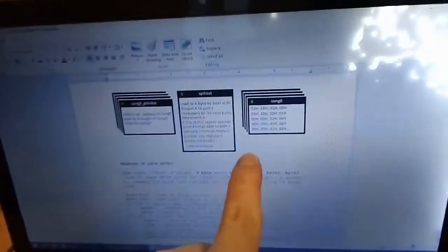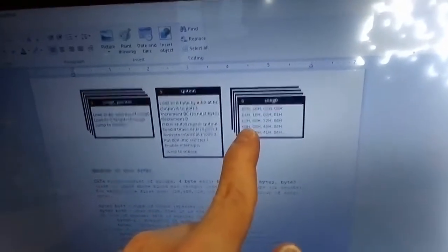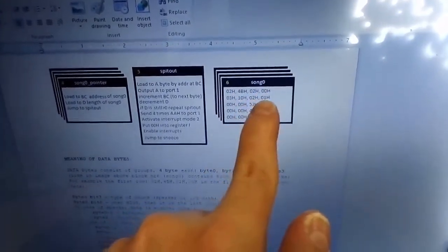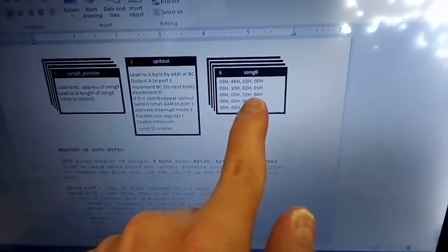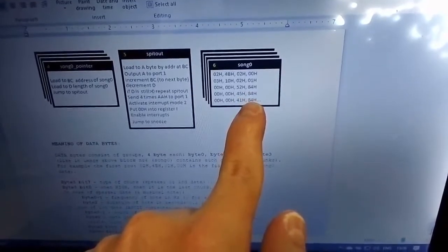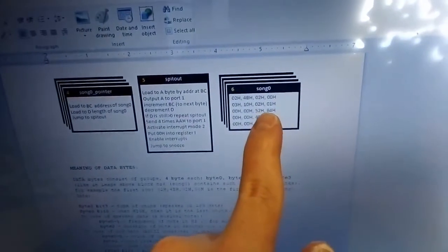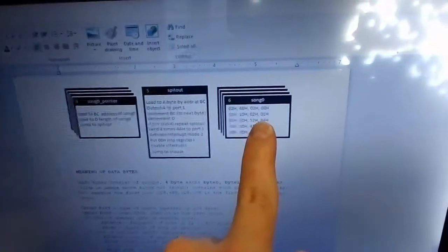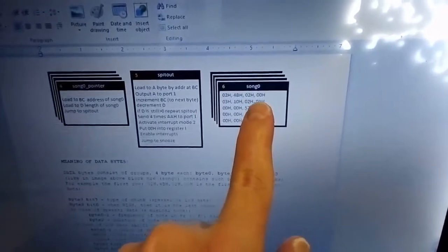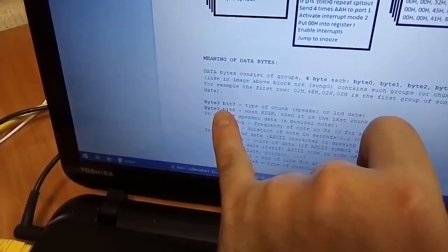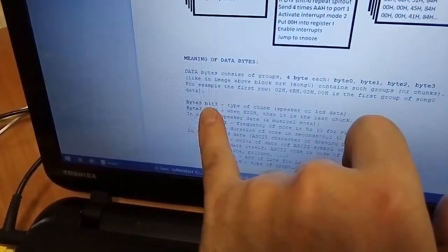That's the default song which plays even if we don't press a button on the keyboard. Then these 2 notes, and then graphic, 5 letters ready. He understands if it is a note or if it is a graphic by looking at byte number 3, at bit 7.